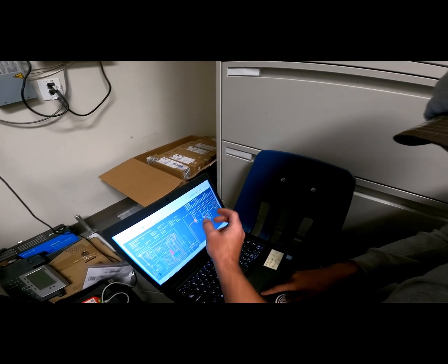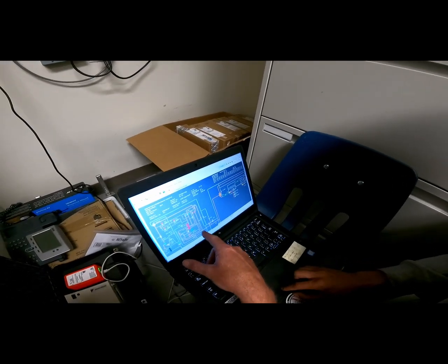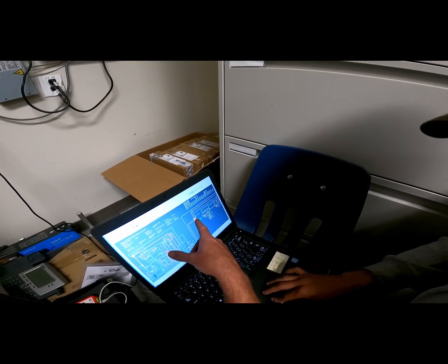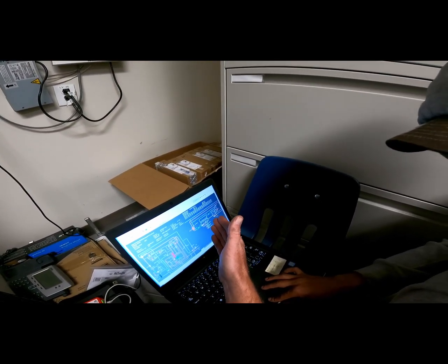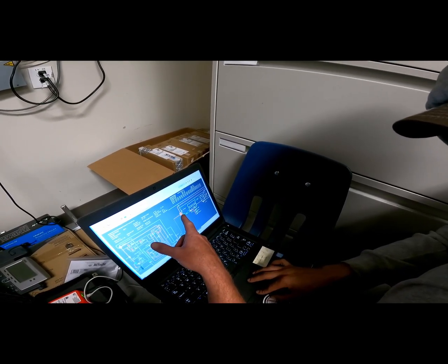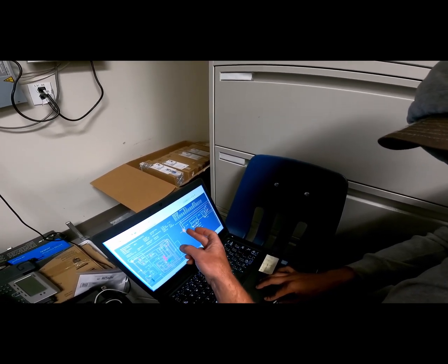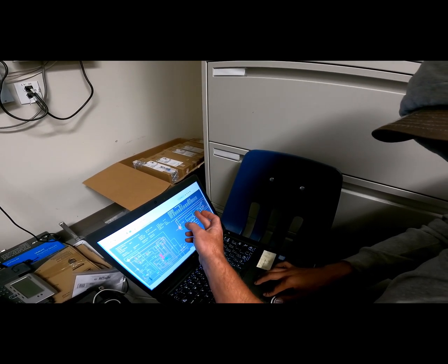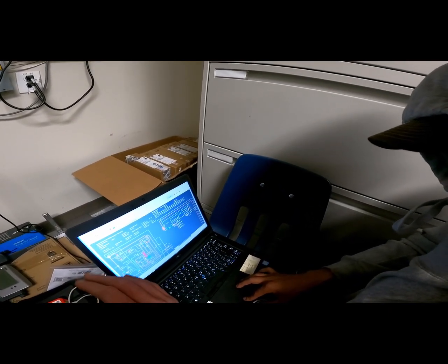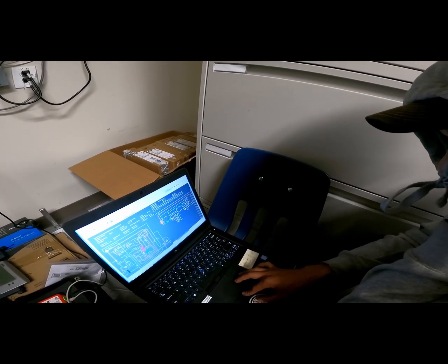These two are subcoolers, so they're taking this, let's see, right here would be a gas. By the time it gets to here, it's a liquid. That liquid comes in here. These units operate a little funky, man. They send vapor and liquid down this one pipe, and then this is a liquid vapor separator. So gas would go out this way to heat, and all the liquid is actually right now falling and going through these subcoolers, and it's subcooling that liquid so that by the time it goes through a metering device, it's already been chilled, so that when it comes out in the fan coil, it's like super cold.